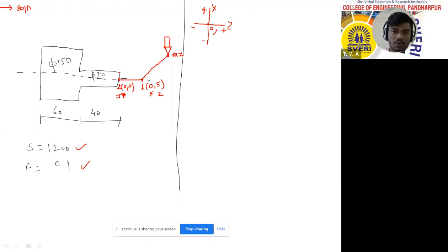This is the third point. So I will travel with which direction, linear or circular? Here you can see the rapid travels from the machine 0 point to point number 1. Then again point 1 to point 2, linear interpolation. Then point 2 to point 3, again linear interpolation, but dimension. What is the dimension of the x-axis?